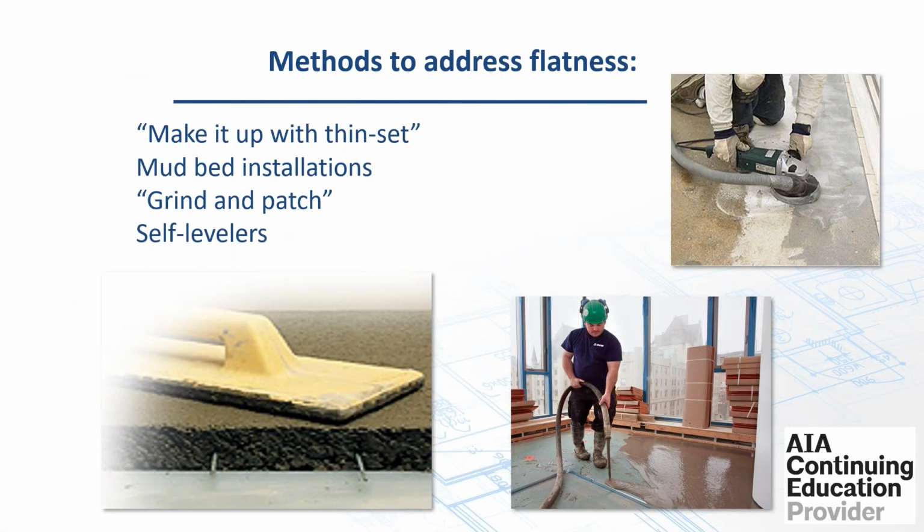Let's talk about some different ways of trying to address substrate tolerances or flatness of the substrate. You can make it up with thin set. No, you really shouldn't. It goes against industry standards, and manufacturers will not warrant their product for a patching compound if it's a thin set. Thin sets are intended to have a tile or something go over them, not to be exposed to the air. So they can be a very weak installation when it's done as well. And more important, you don't want GCs and architects to just say make it up by putting more thin set down. That's costing you money and making your installation much more difficult. If you have the proper preparation done ahead of time, your installation will be 110% easier.